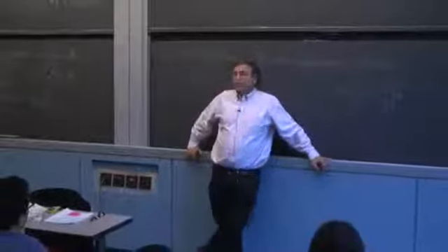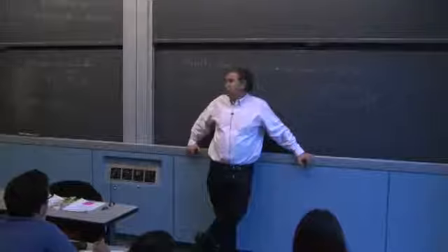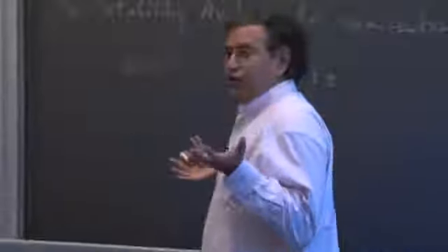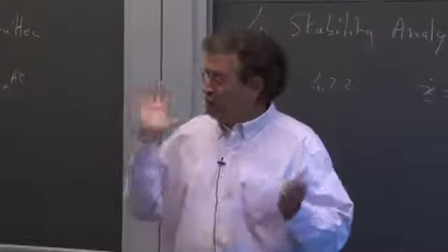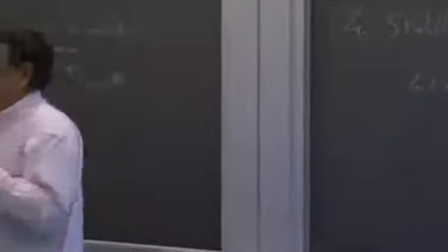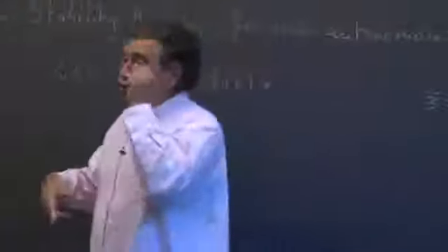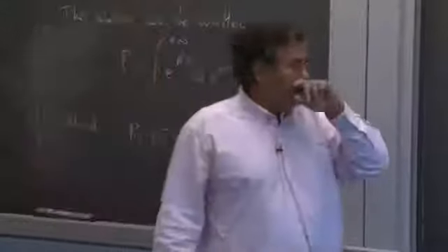So what are the eigenvalues of this system? If you compute the eigenvalues, just get the diagonal here. You have a 0 here. So the eigenvalues of the system are just minus 1, a double eigenvalue at minus 1. So not only are they in the left half plane, but they're constant. The eigenvalues don't even change. So if the conjecture was true, the system would tend to 0. However, of course, the system doesn't tend to 0.